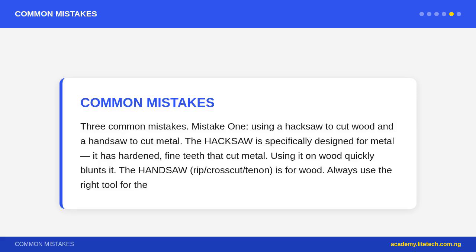Question 3. State 3 rules for safe use of a chisel. A. Always cut away from the body, never point the chisel towards yourself or hold the work in your hand while chiseling toward you. B. Use a mallet to drive a chisel, not a metal hammer, to avoid damaging the wooden handle and maintain control. C. Keep chisels sharp. A blunt chisel requires more force, slips more easily, and causes worse injuries. Never use a chisel with a cracked or loose handle.